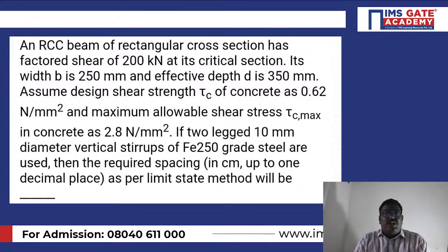See, my dear students, when I talk about RCC, when I talk about shear reinforcement, what is the importance of shear reinforcement? Due to shear, there can be 2 reasons of failures: one is diagonal compression failure and the other one can be diagonal tension failure.